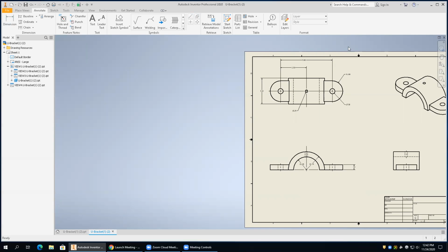You see anything that would be missing if you were trying to draw this? The only other thing that you might say is I might need a dimension over here, but it's implied. Well, the way a lot of people do that, they would say 2 times for 2 holes. So you would put 2x in front of that. So that would say 2 holes at a 1/2 inch diameter.